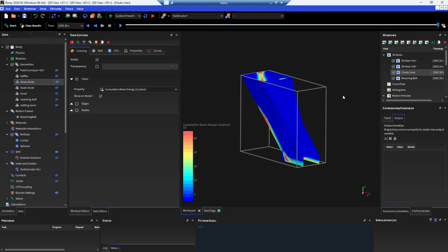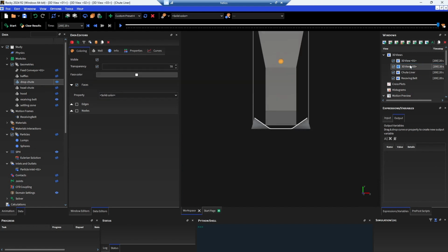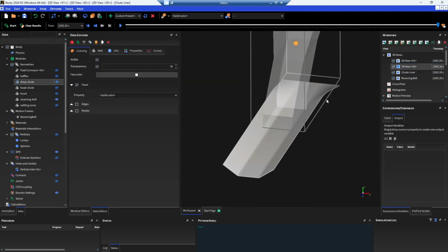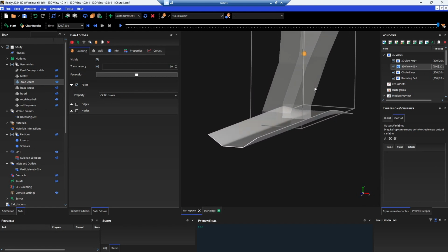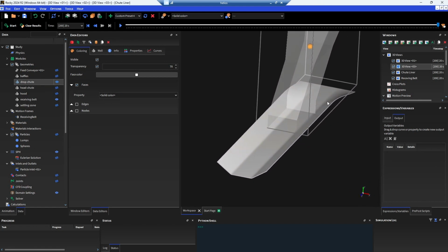Now, one of the other things that we can look at is, of course, how the receiving belt is actually loaded. One of the primary things that we mentioned we want to do is minimize non-central loading, which can cause, of course, belt mistracking. So we want to make sure that the flow is symmetric on that belt and centralized on the outgoing conveyor itself. And there are a few different ways that we can address this particular problem by looking at various different things in our DEM model.